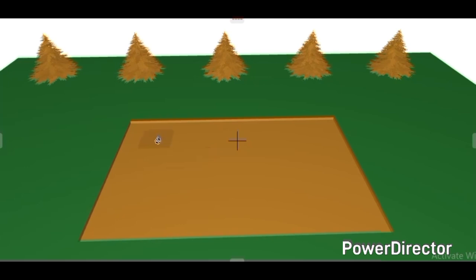and even the average distance that they are being disposed on. So if I have dug this and then I'm going to dispose them here, average distance of 30 meters from the site. Now we talk of heaps. This one is a heap, this one is a heap, this is a heap. And they are on site, meaning we are expecting to use them again at later stages. Off site means they are being thrown away and they cannot be reused again.